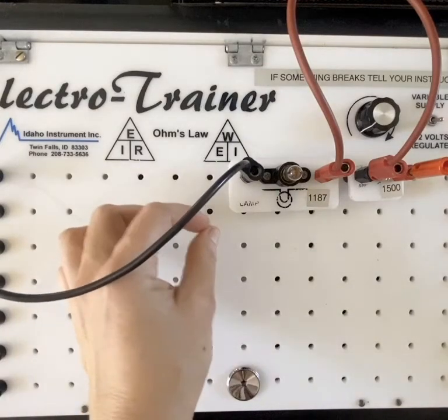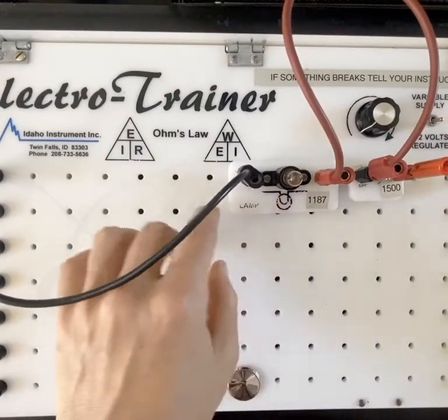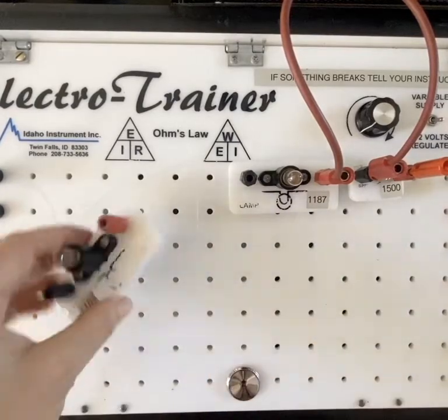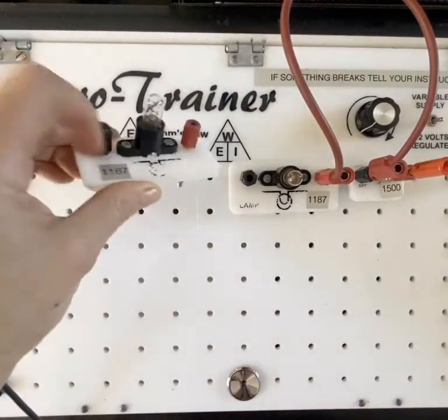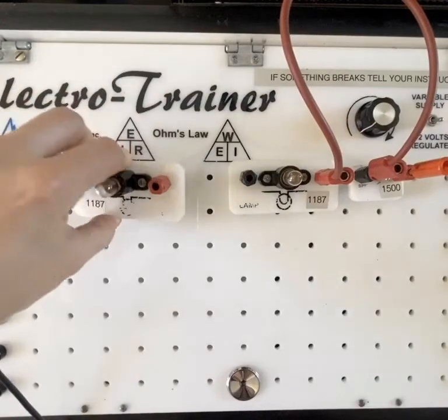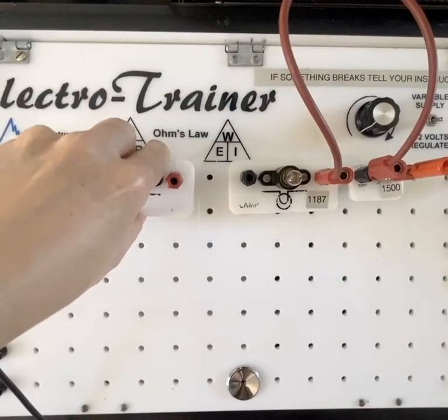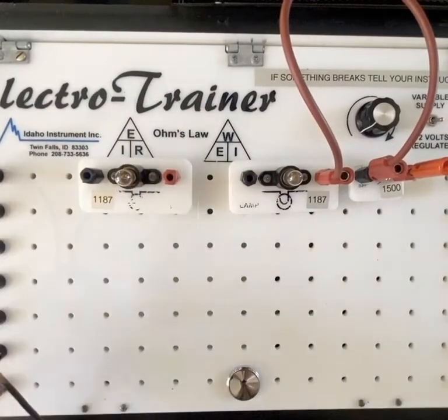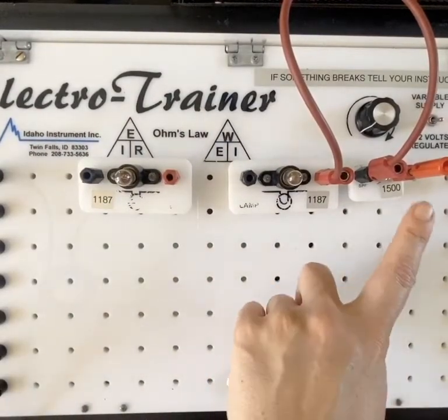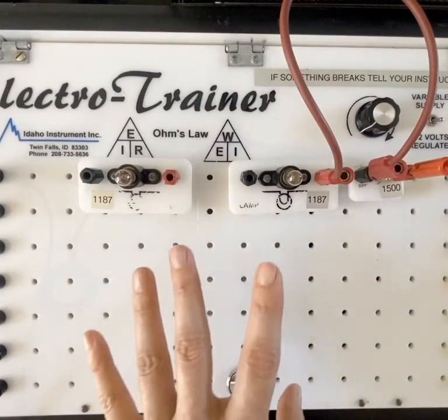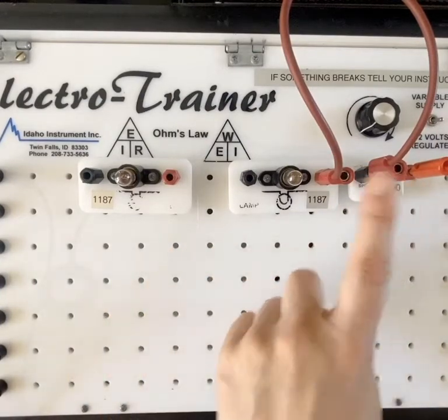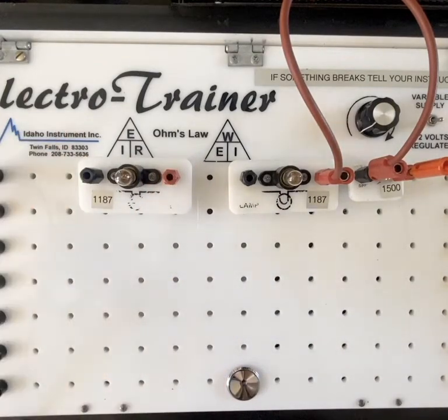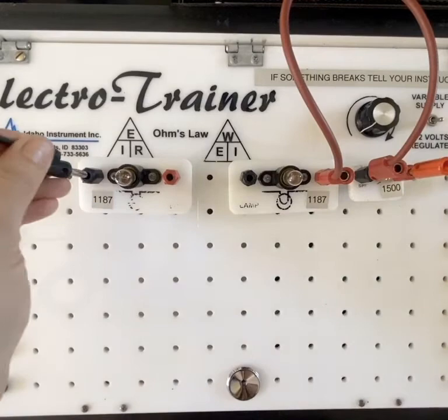So in order to make this from a simple circuit to a series circuit, I'm going to disconnect my ground side here. I could have put it in front, but I'm just going to put the same 1187 bulb, so the same ohm rating, right here next to it. And these aren't always aligned. Okay, so now I need to finish the path. Remember, in a series circuit, I have to have one path into the first load, then out and into the second load, and then to ground. So we'll go ahead and connect our ground.